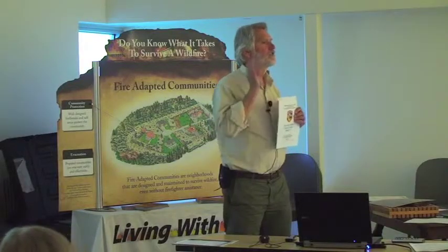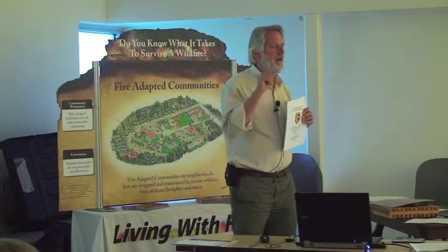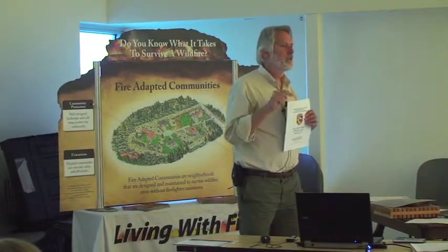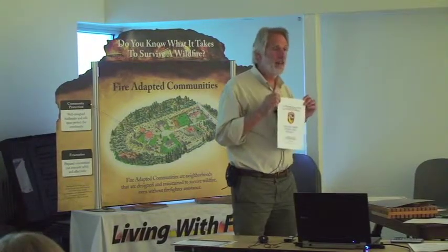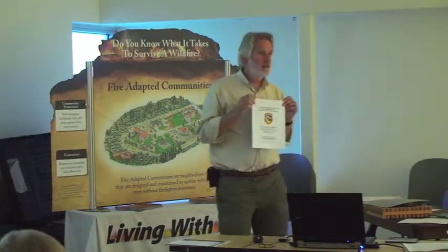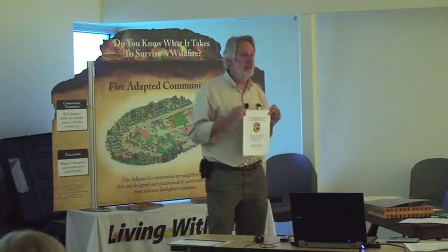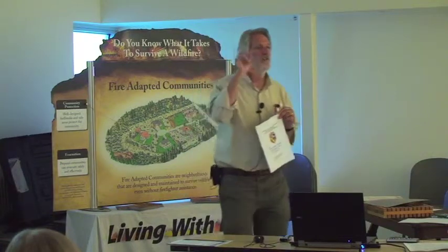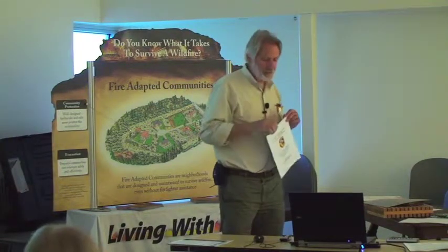The California Code is the ignition-resistant construction guide, so to speak, but it allows combustible materials. Things in this have passed a test, but it isn't a non-combustibility test. It isn't necessarily an ignition-resistant material test. It is a test that evaluates a certain performance to a known fire exposure.